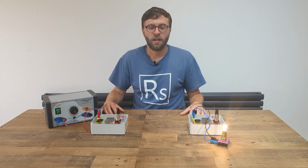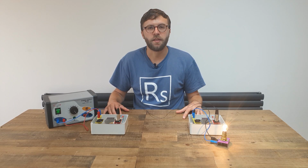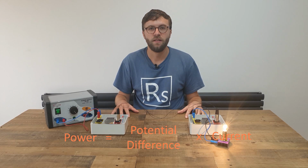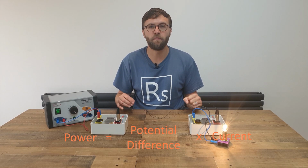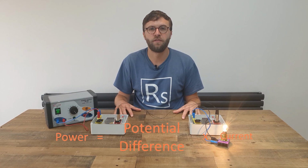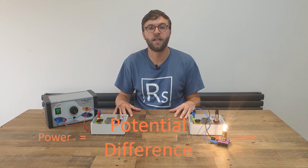So why is that? This is where we need to bring an equation back into the picture. We know that power equals potential difference times current. So therefore, if we're transferring the same amount of power, what happens when we change the potential difference? If I start to increase the potential difference, then you can see that the current starts to get smaller.